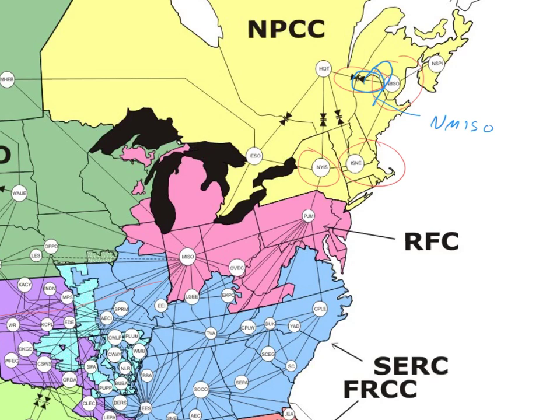A couple other things that's interesting here. Remember how I said, why are we going to run another DC link to Canada? Well, look at all the lines going to Hydro-Quebec territory. They're all DC, right? That's because, again, they run asynchronously from their neighbors. They don't have to run at the exact same phase shift.